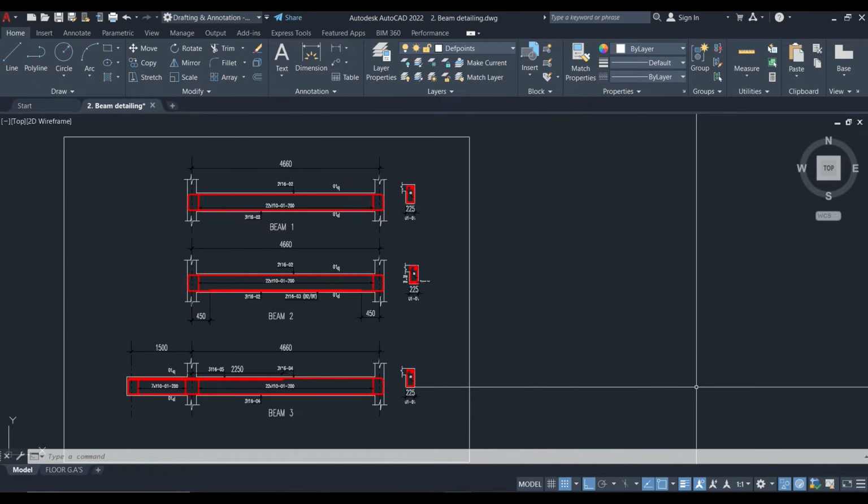In this video, we are going to be using a simple format that is slightly different from what we have in BS 4466, but the idea of every bar bending schedule is to be able to quantify the reinforcement in your structural details, and then to serve as a guideline for the iron benders while they are cutting the reinforcement.